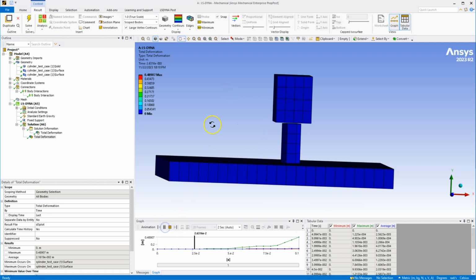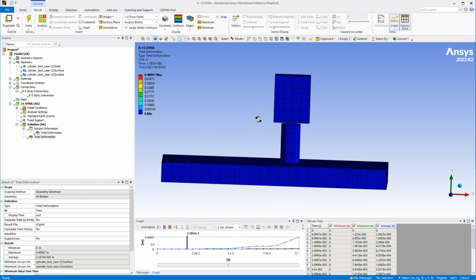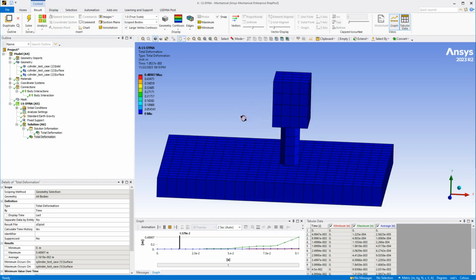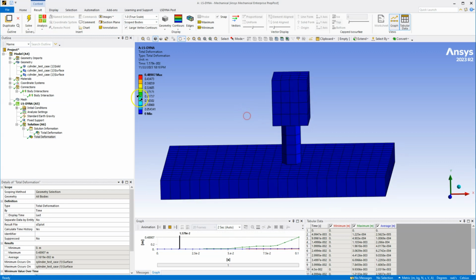So if I hit play here, it's coming down, hitting the cylinder, and it's shooting out to the side. That's because I have a frictionless contact. There's no energy lost in the sliding, which isn't very realistic. So let's add some friction to get it. And we're basically going to add some stuff to the simulation to get it a little more realistic.